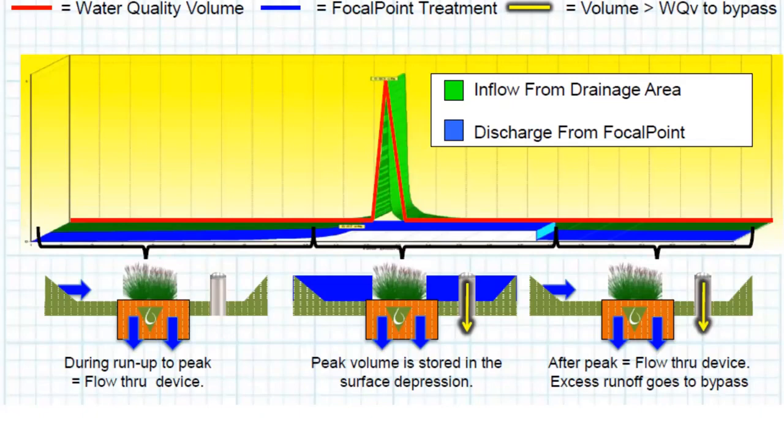So that rain garden or bioretention can handle so much rain. And then at the point where the soils are flowing at their peak rate, that's when you actually get your surface storage, right? So then the basin fills up with water. And if it's a really heavy event, you might get some bypass that goes in your overflow. But after the storm calms down, eventually that engineered soil will drain out that entire basin.